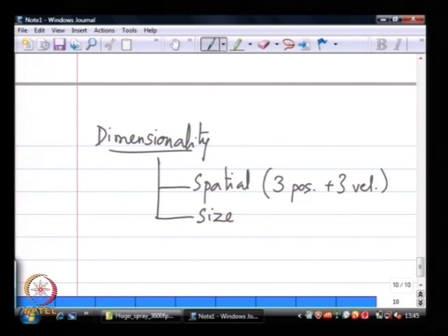It is a real number between some lower limit of what is possible, and we will talk about those also, let us say 0.1 micron. There is no way conceivable that this perfume spray would produce a drop less than that, and there is also an upper limit, or the upper limit could be infinity. The simplest understanding there is that our upper limit is as big as the hole on the perfume bottle. I cannot produce a drop much bigger than the hole on the perfume bottle. So, I have a natural upper limit in a perfume spray. Between this lower limit and upper limit, the diameter of any one drop could be a real number.